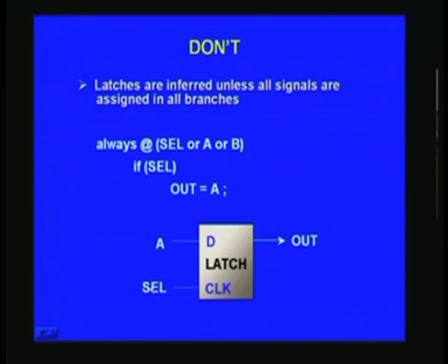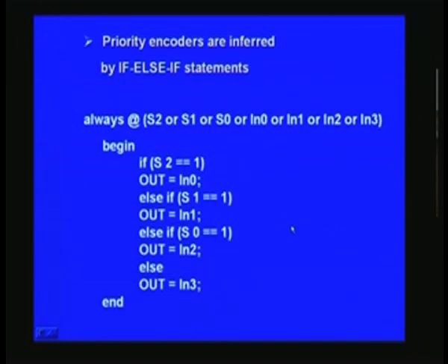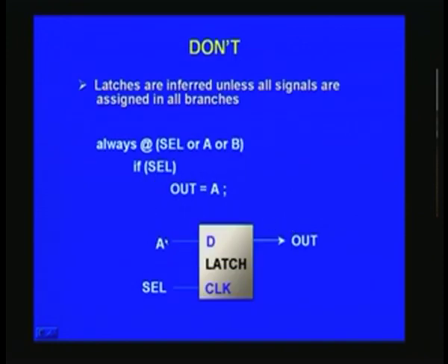That is, when clock is not applied, whatever is applied to A will without any hindrance appear at the output, and it keeps on changing here, and if you have mixed it with the synchronous circuit, it may latch, register at an undecided point. So you should avoid these latches here, and the reason for creating a latch is you have omitted else.